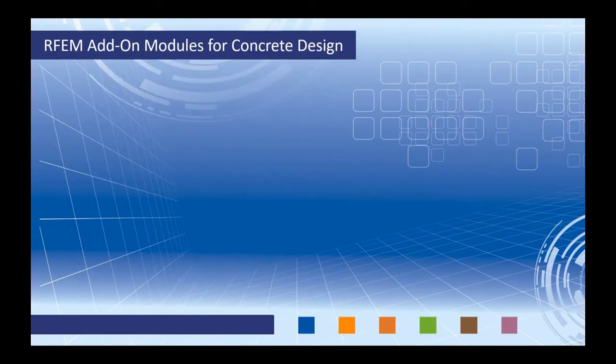So to begin with, RFEM is our main program. This allows us to fully model and load the structure. We can create load combinations according to the ACI 7, NBC standard, and run a full analysis. With the analysis, we're going to get things like internal forces and deflections, and we can take those, as I mentioned before, into our own in-house tools to do the reinforcement design.